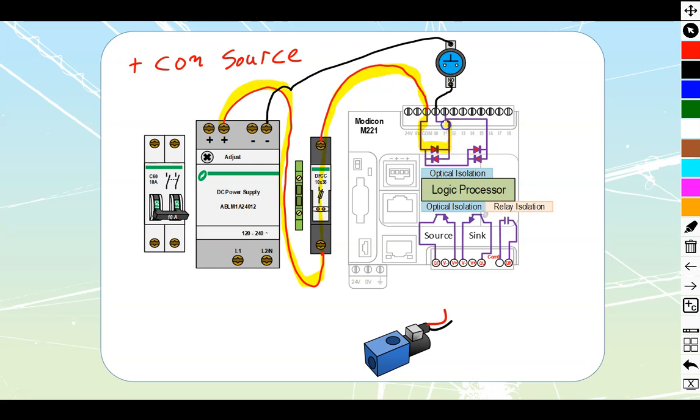This LED inside of that package, back-to-back LEDs, travel up through. We're able to make it through that push button when it's pressed and carry it all the way back to the source over here. This is going to be referred to as a sourcing type of input. Whether we look at this one or the previous one, the really important thing to note is that either of them is going to light up one or both of the little LEDs that we have inside of there.